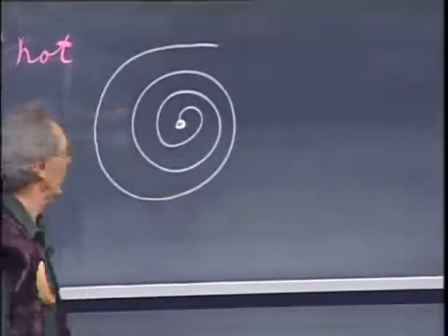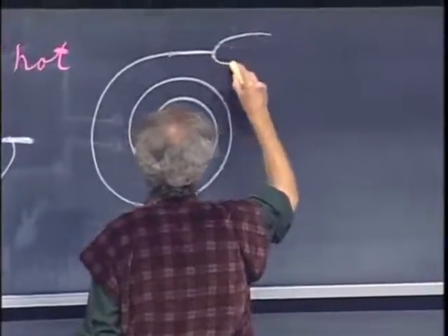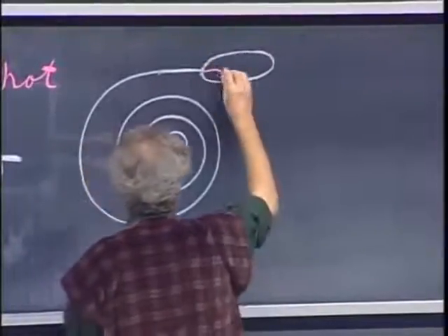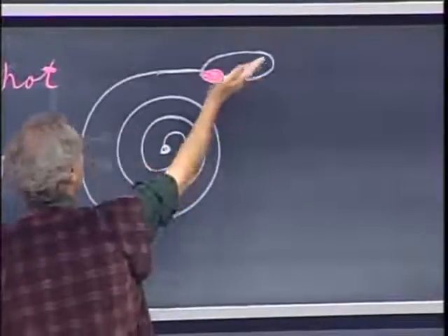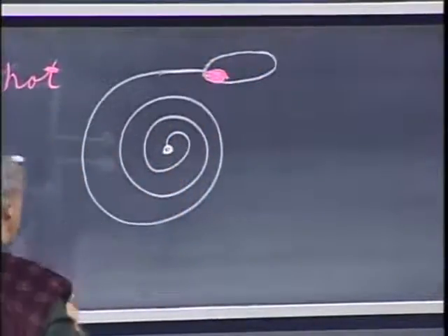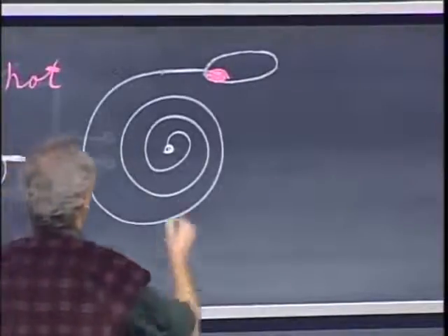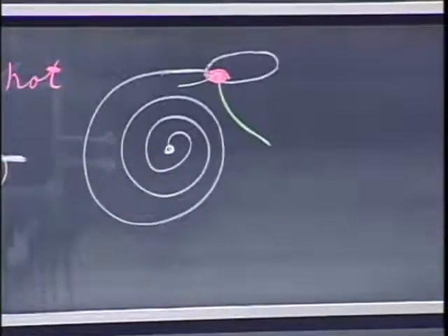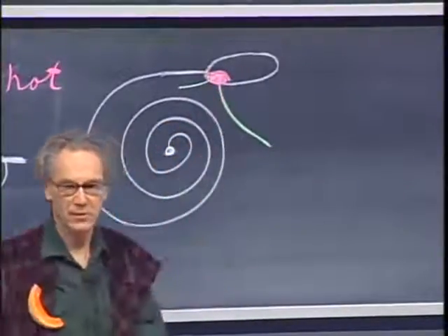Bimetal. And at the end here is a glass container, and there is some mercury. And the mercury is here on this side, because notice the way I have tilted it a little. The mercury rolls to the left. And there are here 2 wires, electric wires, one here and one here, which go to the heating system. And so when the mercury is here, which has a good conductivity, the heater is on.